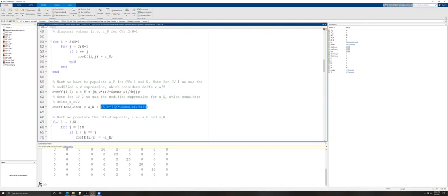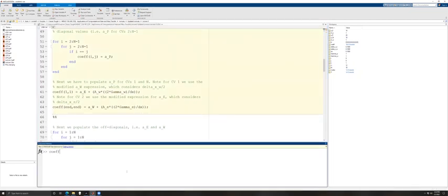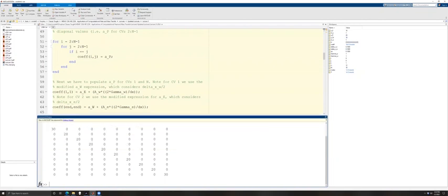So coF11 would be the first entry of our coefficient matrix. This is A east plus 2 times A west. Now I just did 2 times what we had initially existing, because we have our dx per 2. The last entry for our coefficient array, I did A west plus the modified A east, as we saw when we evaluated our 10th control volume. So we can come up here, look at our coefficient, and we see our first and last coefficients do differ from those of the interior. And this is a very good sanity check. If you had all 20s, something's going a little bit funny.